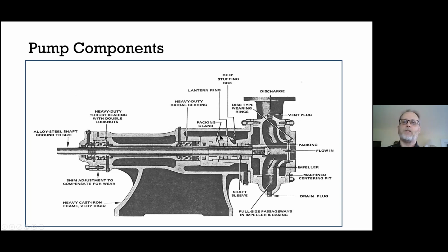We also want to prevent leakage, and one of the main functions of the packing gland, and there's two really, but the key is we don't want fluid to leak out of the volute along the shaft. First of all, it could damage the pump itself, but you're not going to move any water that way. So you can see on the cutaway, this is a packing style of seal with a lantern ring. Very difficult to see, but the lantern ring is right in between. So we've got three braids of different rings of packing on either side of the lantern ring. And then the packing gland follower ring, stuffing box, this is squeezed on, that holds all of this inside, and you can see the actual body of the pump here, holds that inside.